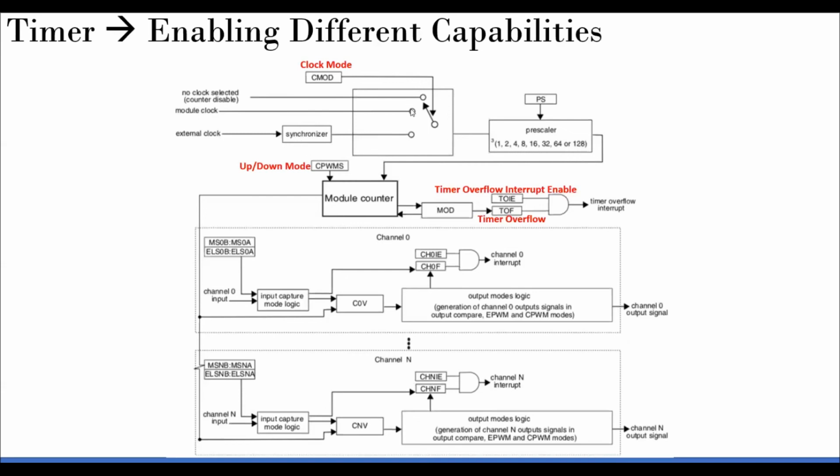So you can divide your clock frequency by one of these values. That's again up to you. You write to the register, that's all you need, and the internal hardware is already done. That is again, I keep on reiterating, the beauty of a microprocessor. It is a software controlled digital circuit. So you write to this register, it will select the appropriate clock. You write to this register, it will select the appropriate clock frequency division.